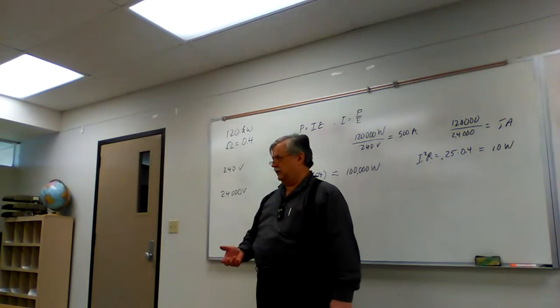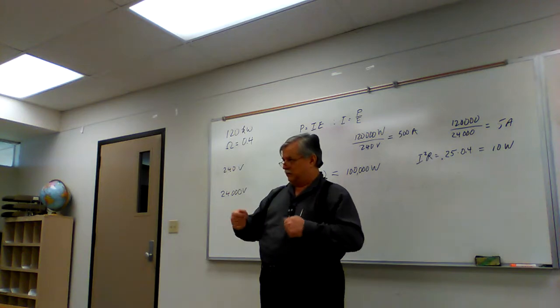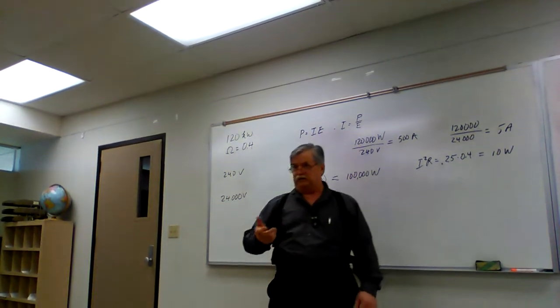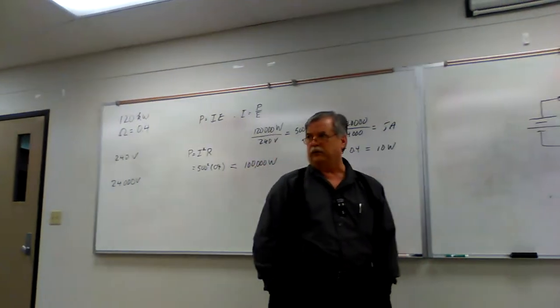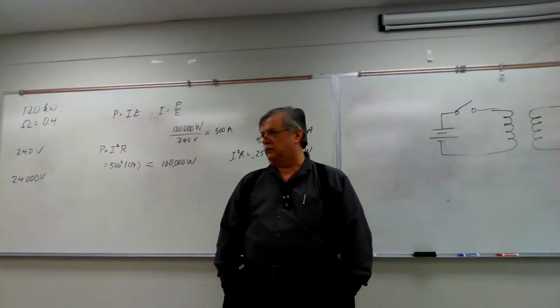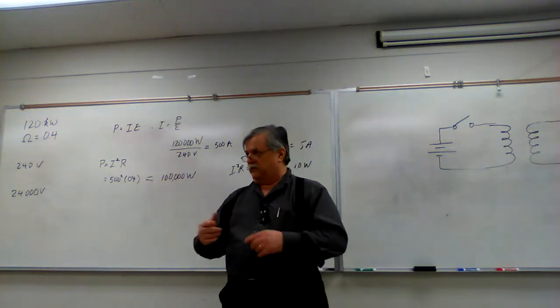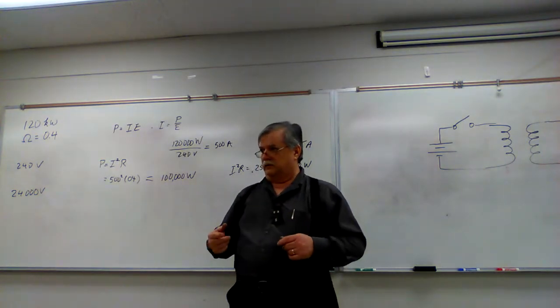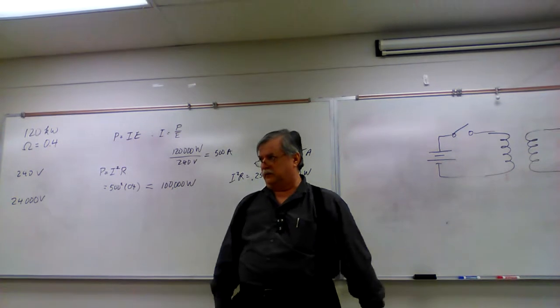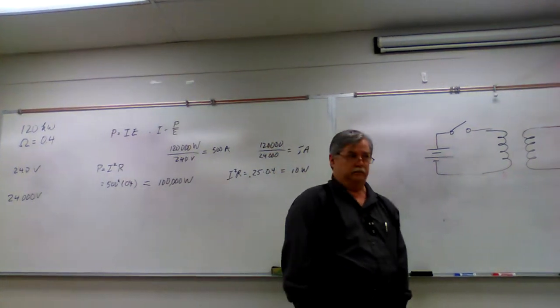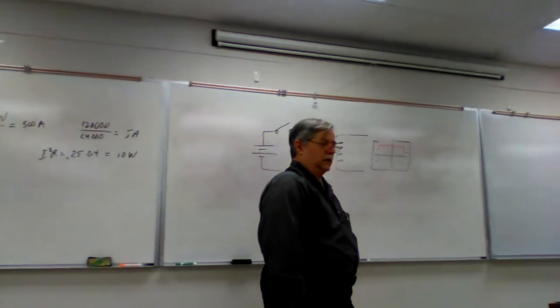Now, within the limit of the fact that the thinner you make the wire, the resistance is going to go up, and eventually you're going to start burning out the wire, so there's a limitation there. But in general, you would get more magnetic field with more turns in a shorter space and in a smaller diameter.